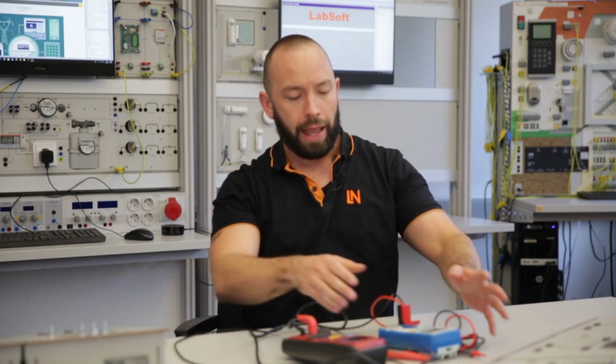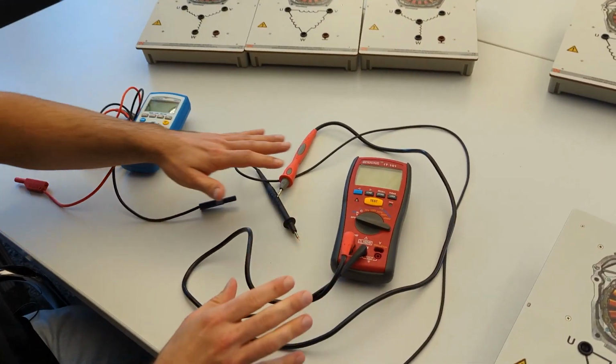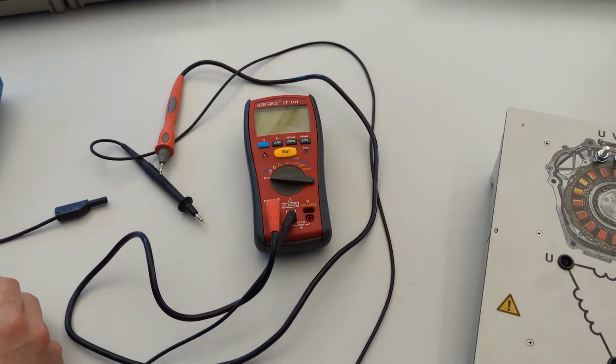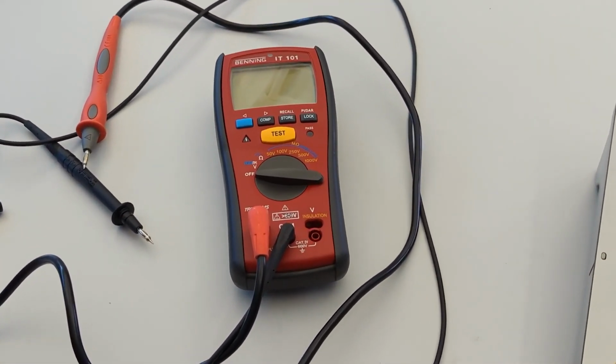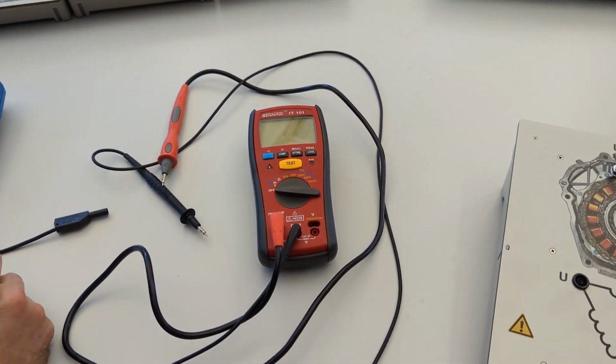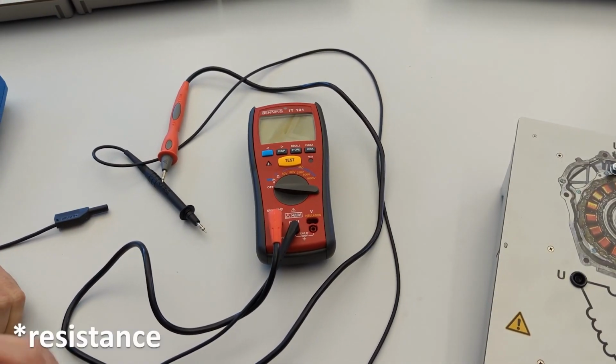Like I said at the beginning, today's topic is what kind of measurements we can do at the electric motor in order to find out if it's in good condition or if something is wrong with the motor. Let's first look at what measuring tools we need, and this is pretty basic. On the right-hand side, you see our insulation meter. It can go into a very high area, the mega ohm area, where we measure with a really high voltage.